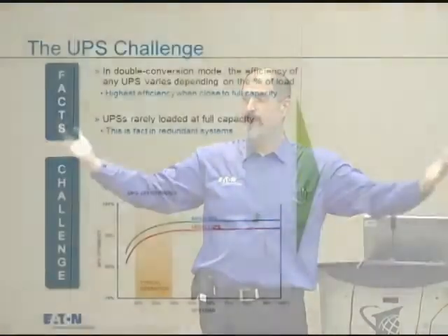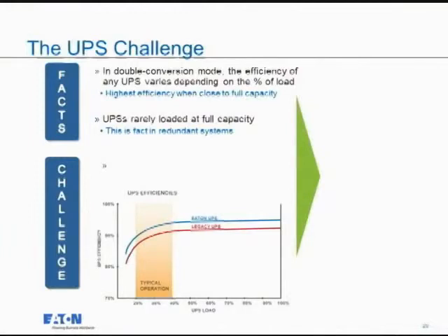Does that make sense? So in that scenario, by design, the maximum load I put on A or B normally is 50 kVA, 50%. So by design, the maximum becomes 50%. Well, nobody wants to run at 100%, right? The traditional 20% derating factor comes into play. So really, optimally, my systems are running at 40% by design. Well, what does that do from an efficiency point of view? Really, really throws that out of whack.